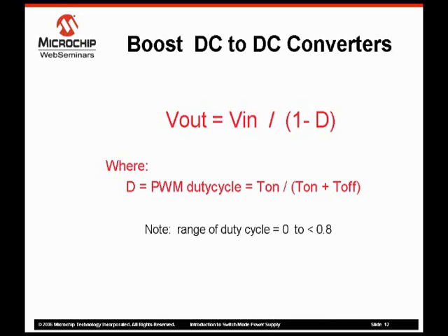If the inductor current does not fall to zero on each PWM cycle, the magnetic core can accumulate a magnetic flux that saturates the core material. Core saturation will cause the inductor and the circuit to fail.